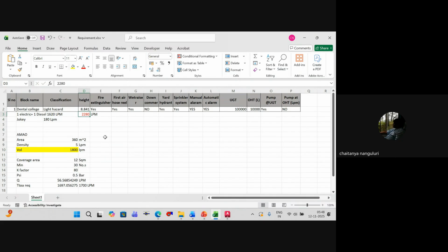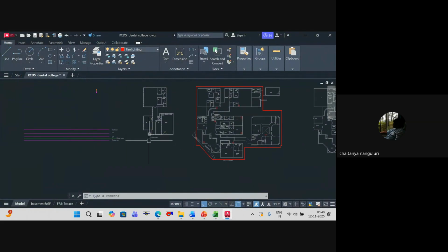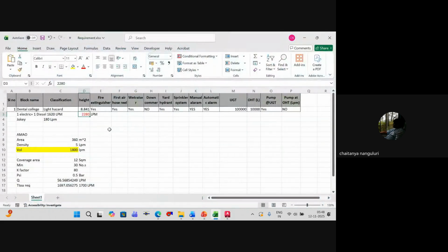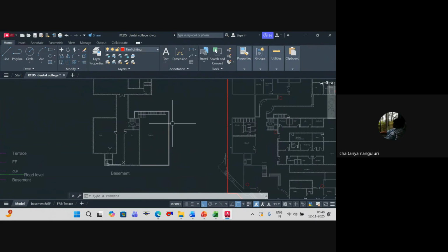Yes. Okay. Then coming to the next element that we have to refer to, the other important thing that we have to worry about is the pump capacities and the design and location of your pump. One is vastu, and the second thing is that the pump room entry should be directly from external wherever possible. If possible, anyone should be able to reach the pump room directly from outside. You need not enter through the building; try to avoid entry through the building into your pump room. Understood?